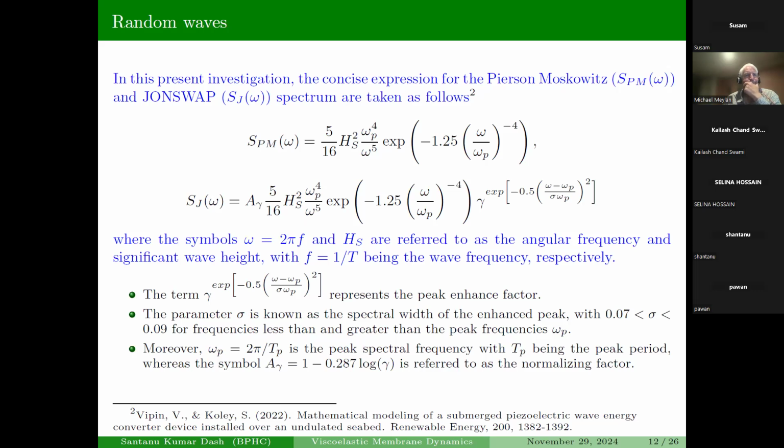The idea of the original Pierson-Moskowitz spectrum is the assumption that if the wind blew steadily for a long time over a large area, the waves would come into equilibrium with the wind. This is the concept of a fully developed sea. Several representations have been made. The initial representation was taken from the Phillips constant, and later, to effectively incorporate the significant wave height, the corresponding wave period has been taken.